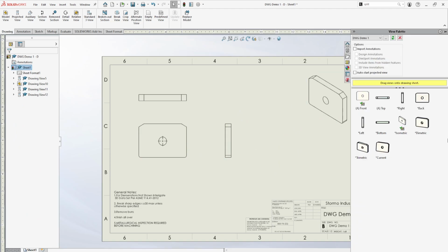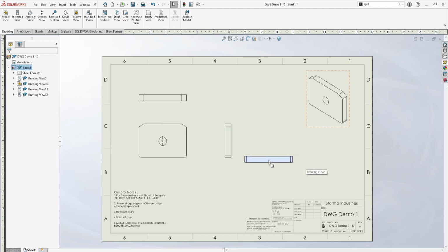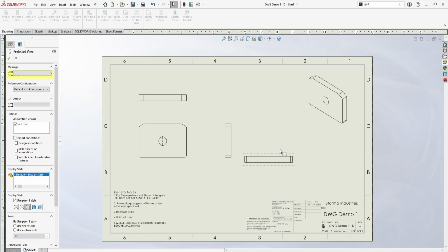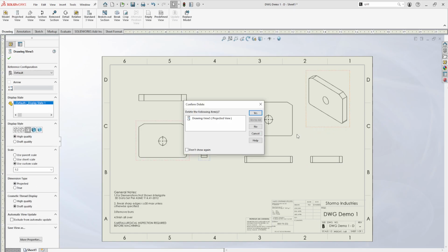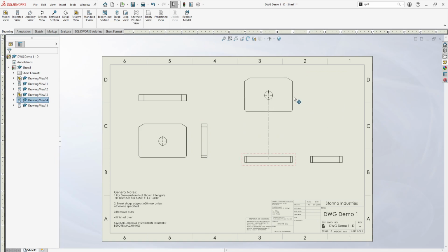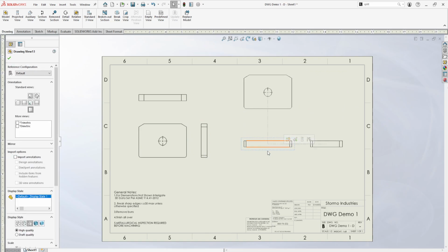There are some occasions where it's nice, like over here, to be able to see which face you're trying to grab, because you could make it so that your bottom face is considered your front, and then use a projected view to make your own custom version, such that this would be your front, this would be considered top, and this would be right. So you don't always want to necessarily have to rely on these standard things depending on what planes you started your drawing on.